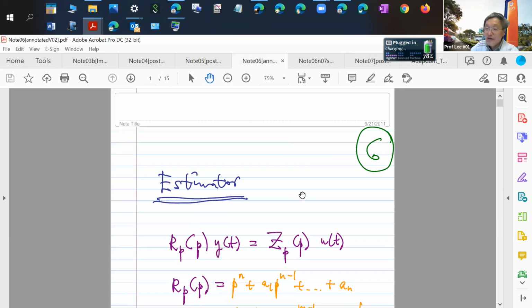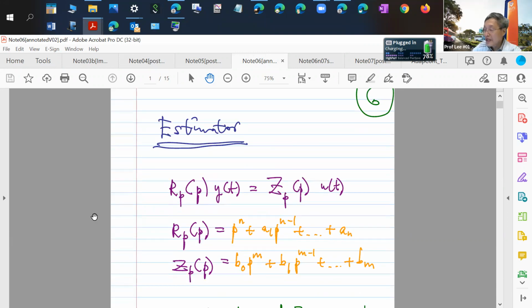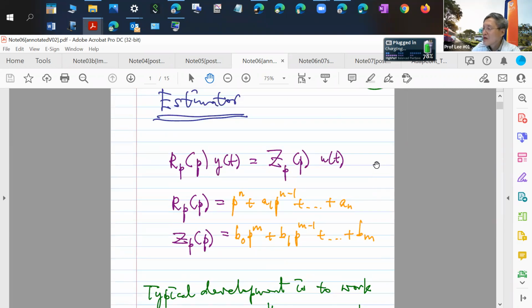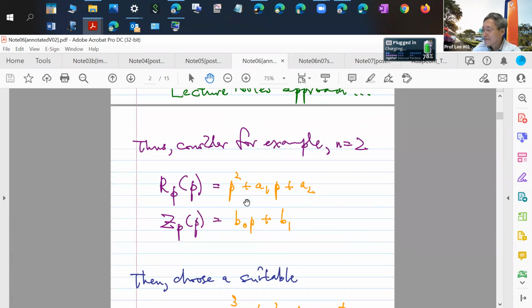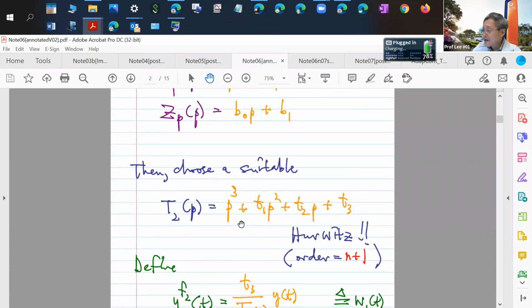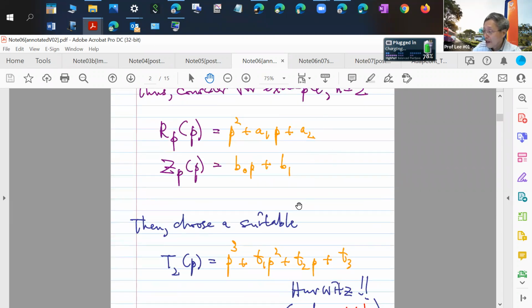Okay, so as I said, I promise you when I uploaded it, I said all these are not for exam. So similarly, you can have a system. You no need to go ahead and try to use the Kalman-Yakubovich lemma or detailed signals and systems. You can say, look, supposing the system is like that. I don't even rearrange it in monic form anymore. I just leave the parameters as they are, because then you can rewrite the system, right? For example, you can rewrite the system, then you can basically choose a higher order filter than whatever is here.